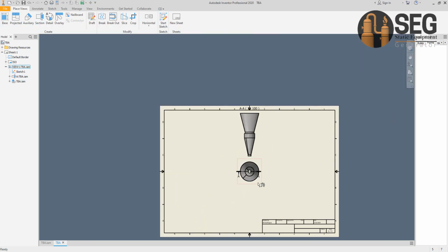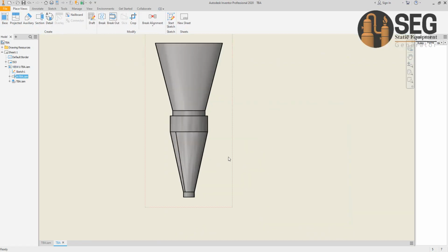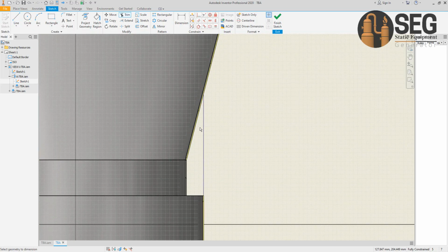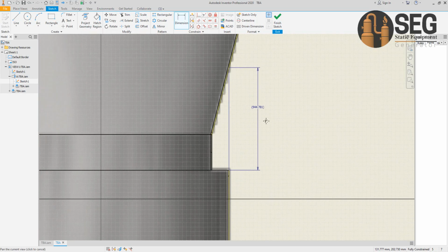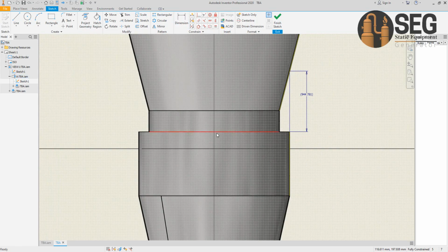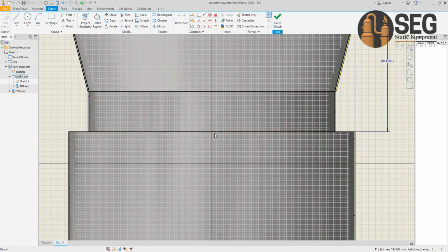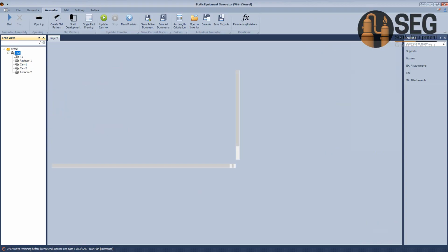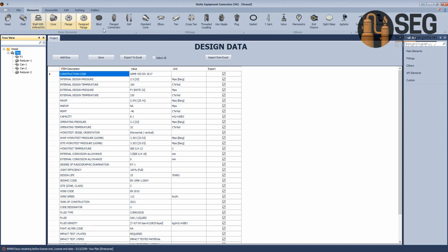And from this section, let's make a sketch to measure the required distance of offset. If we measure the length of this line, it's with that value. So if we move the connection point here down to be with that value, let's try that. From here, let's select the equipment, and from here, let's add a gap.